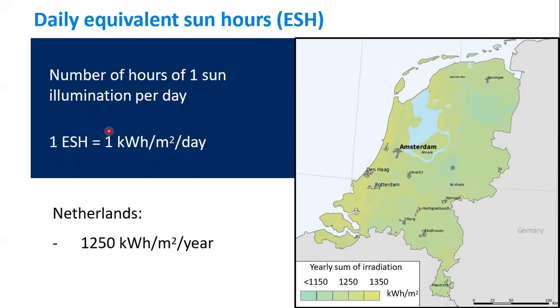So maybe in the next chapter, inshallah, when we are going to discuss together a typical data sheet for a solar cell, whenever you have I-V characteristics or an efficiency or an output power, any of these parameters are measured under what's called the 1 sun condition. This 1 sun condition is equivalent to 1,000 watt per meter square.